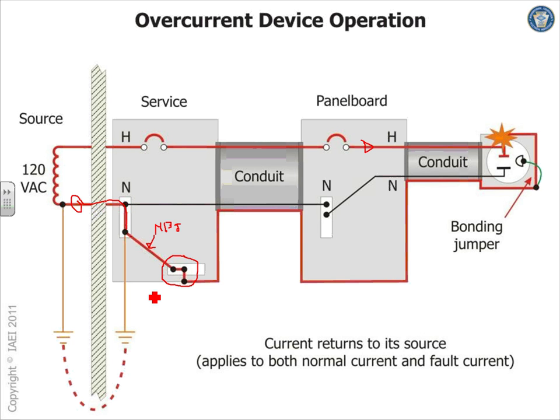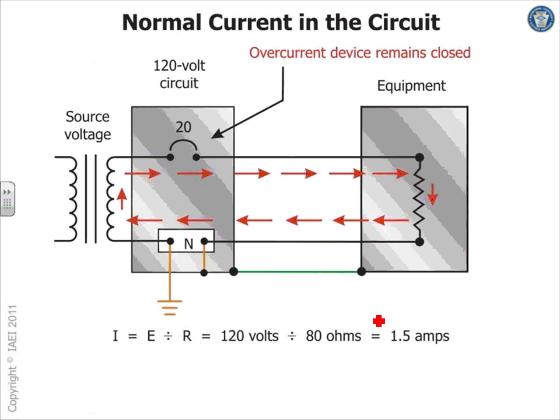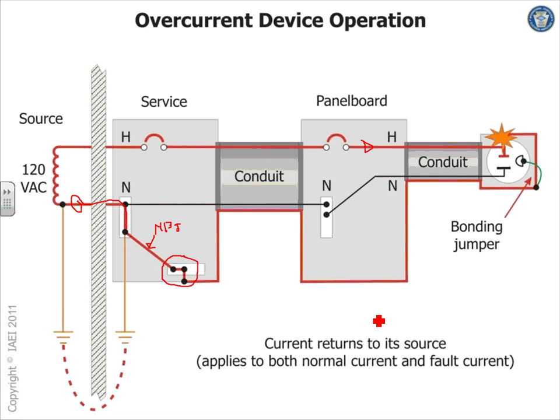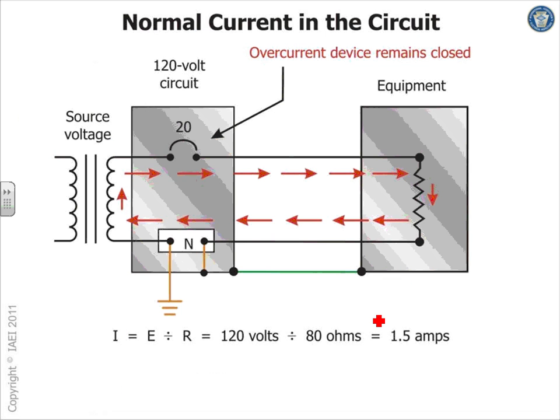So now if this is grounded and bonded properly, you could do two things. One, minimize the shock hazard because it trips fast. Number two, also minimize the arc flash hazard, which could burn your building or kill people. Does that make sense, guys? I hope you understand. I gave you the big picture because we could get stuck with all these details for a long time before you even reach the whole big picture, guys.